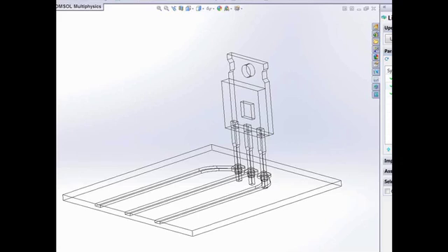Now you could name this anything really, as long as it's set up inside COMSOL, but the live link interface creates a name that is based on the SolidWorks name of the dimension. And then this parameter will appear under the global definitions of your COMSOL model. And this is where the COMSOL solver can drive the parametric sweep by changing the value of this.